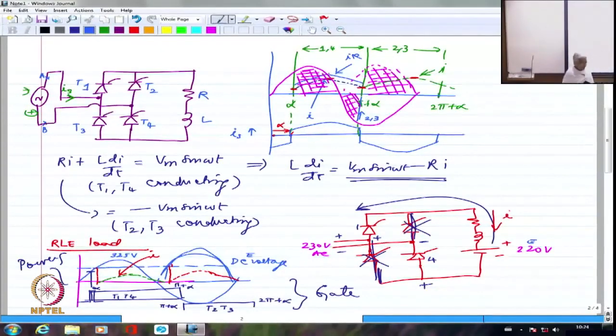So if I actually look at fully controlled converters, the supply side current, right? When I didn't have any of these rectifiers, if the supply voltage is sinusoidal, the supply current will be sinusoidal. R, L, C, whatever you connect, it will be good. There is no problem. The moment I connect a power converter and I intervene with the switching on of one device, switching off of another device and so on, the current wave shapes get completely modified. They are far from being sinusoidal.